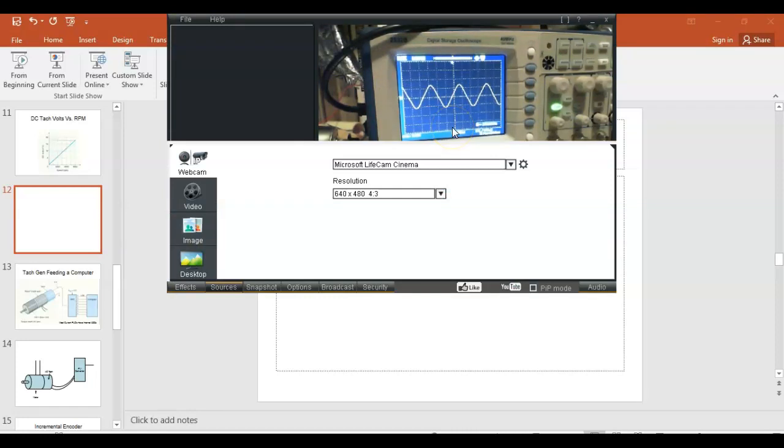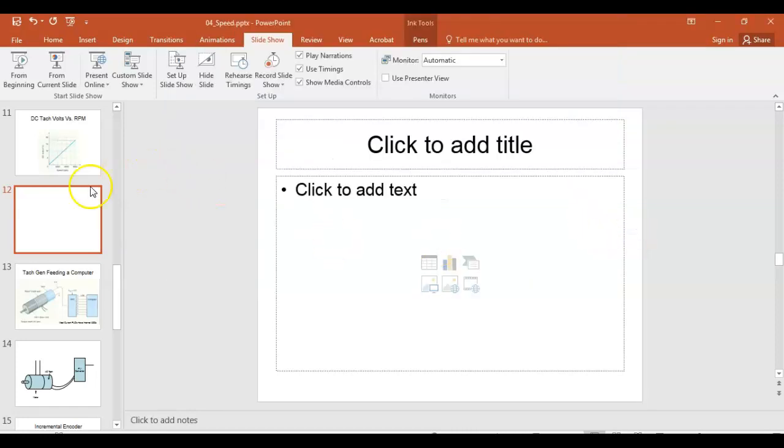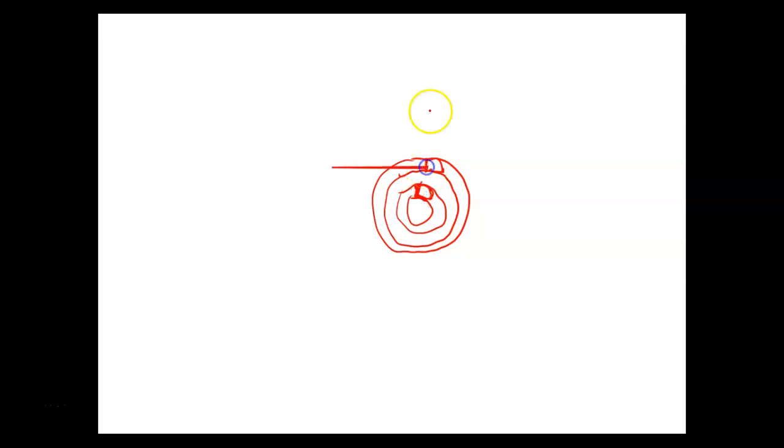So what they have on an AC alternator is slip rings on the back, and they're usually mounted horizontal like this. And then they have two brushes that ride on it. What these two brushes do is transfer the DC into the rotor. But it's not going to be nearly as much current as we're trying to get off the stationary part, right? So what usually happens is these brushes wear out. So normally you take that thing in